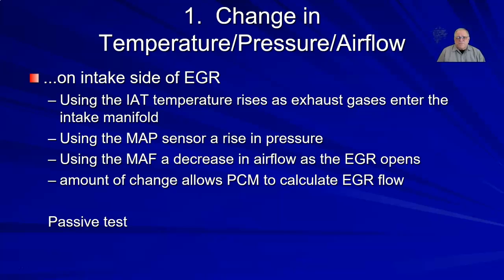I want you to pay attention that we are calculating EGR flow. We are not measuring the EGR flow. Ford is the only manufacturer that I've ever heard of that actually measures the EGR flow with their DPFE. However, all of the Ford techs that I've talked to say that if there's a code with the DPFE, it's normally a faulty DPFE, not a plugged EGR passage.